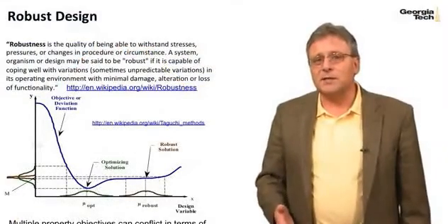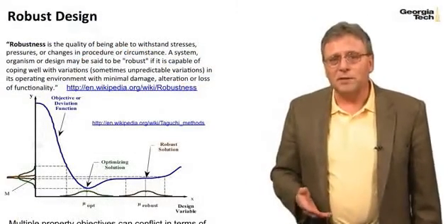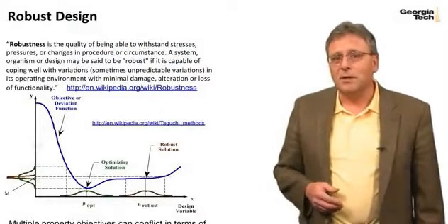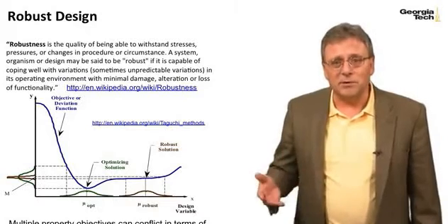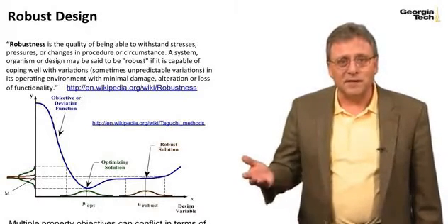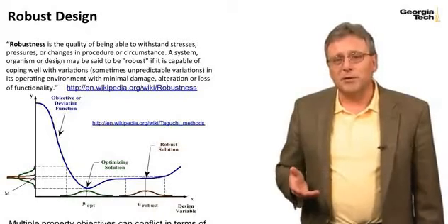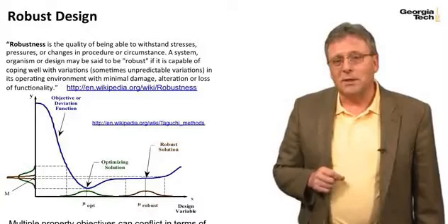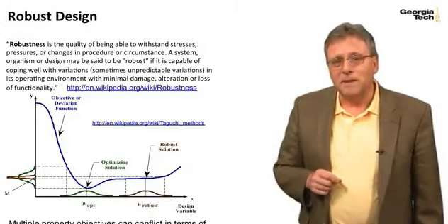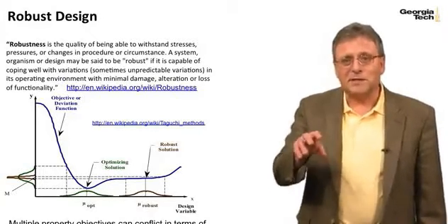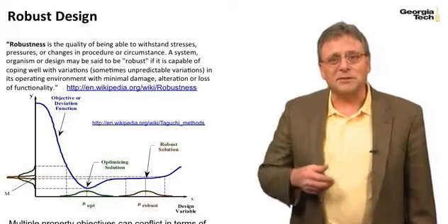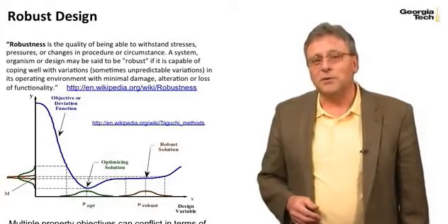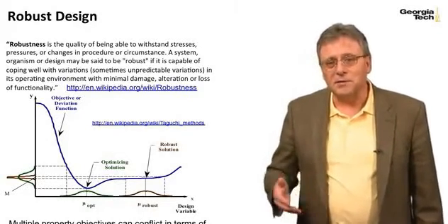To that end, we can consider extending the robust process control methods that Taguchi introduced some 30 years ago to the way we design materials to be robust against variation of design. So design variables for materials might include our target microstructures or structural elements at each level of hierarchy. For example, reinforcement phases, interfaces, grains, etc. And how those would vary according to typical processing or synthesis routes.